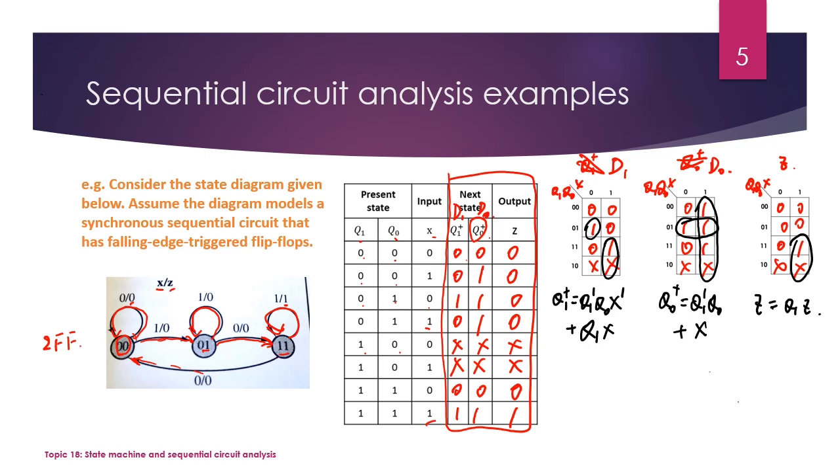And if you use other flip-flops, you need to add columns to figure out the input values of the flip-flop. So here we just still assume we are using D flip-flops. These are the most commonly used ones. Then this should not be Q1, it should be D1, D0. So that's a mistake I made.